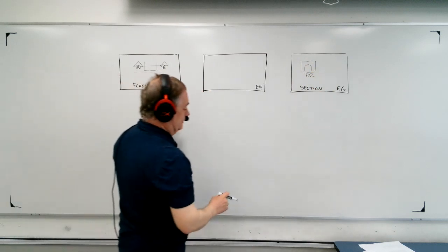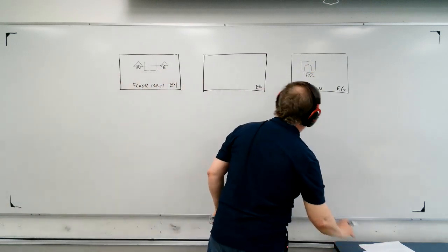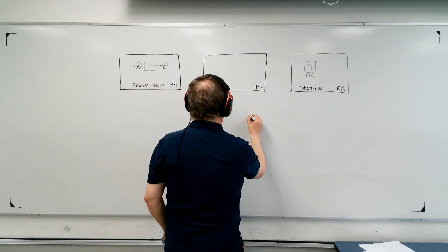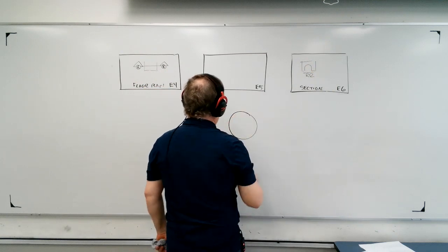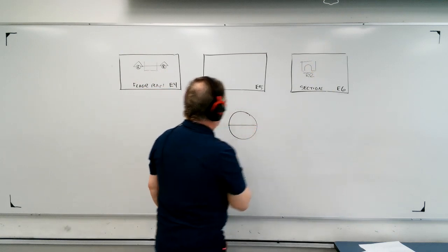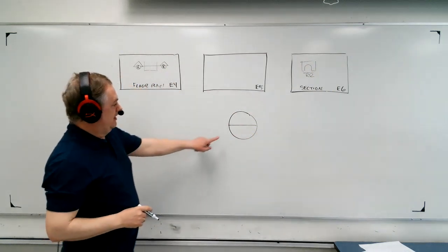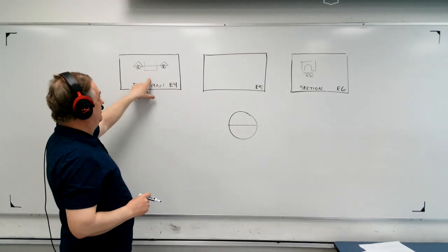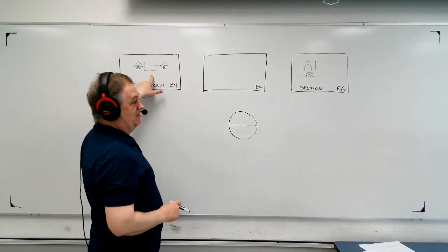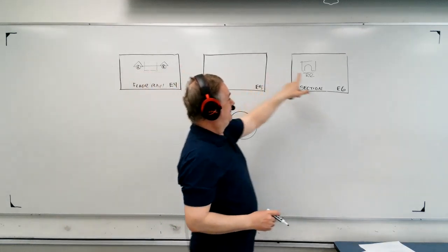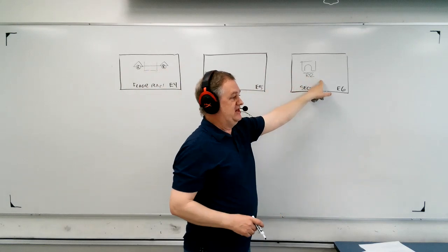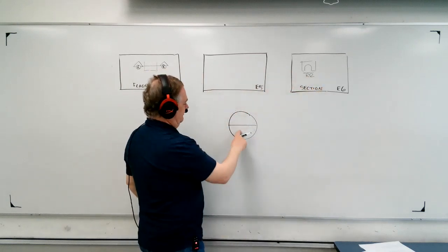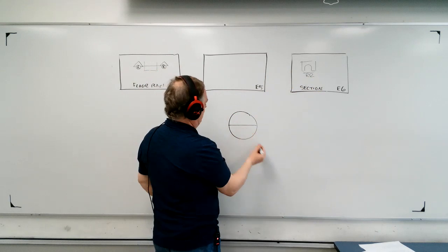Now, if you look at this section symbol, this is how they're actually drawn up. They make a circle. Sometimes they're only divided in half. If the floor plan, where the thing you want to describe in better detail, and the section are both drawn on the same page, then you'll see it like this, and they just write the actual page number here.